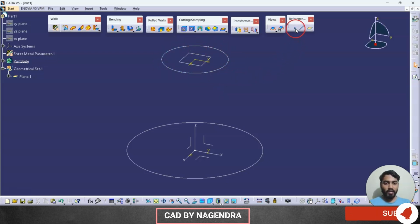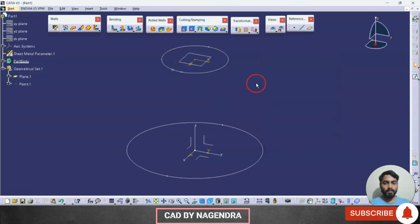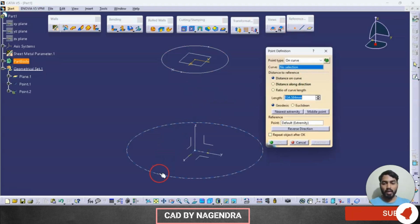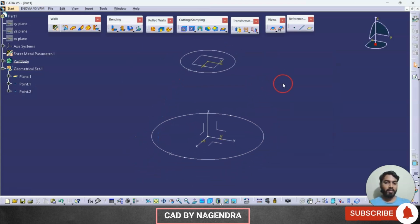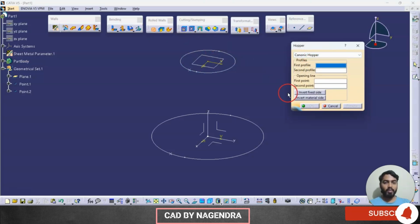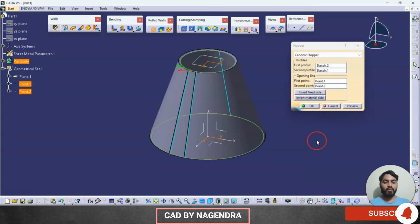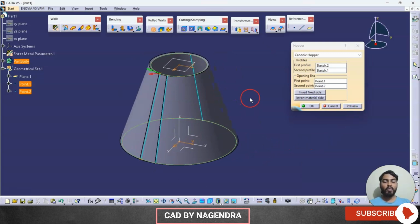To create a 3D point, we go here to reference elements, reference point, somewhere here like this. Let's say okay. One more point we want on this curve, with reference to this point, straight to that one point will be created. Let's say okay. Now we can go with hopper, canonic hopper. The first profile is this, the second profile is this. The first point is this.